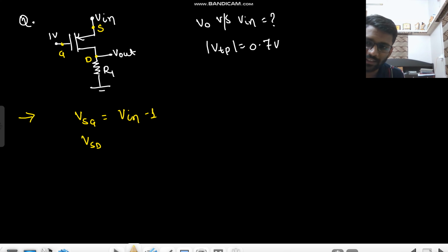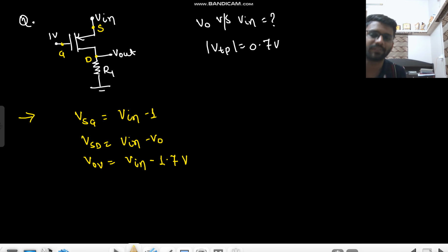What is your VSD? V in minus V out. What is your V overdrive? That is V in minus 1 volt minus mode of VTP. That means 0.7. So it would be V in minus 1.7 volt. Okay.